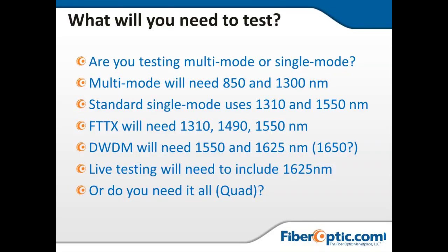Now from the house, what we're typically going to do is shoot up towards the head end. Any information we need to send back, we will transmit at that 1310 nanometer wavelength. So what we're trying to illustrate here is you've got the 1490 coming down, you've got the 1310 going back up the same fiber. Those two different wavelengths allow us to use the same fiber and transmit data in two directions.